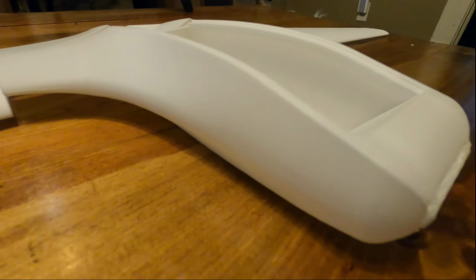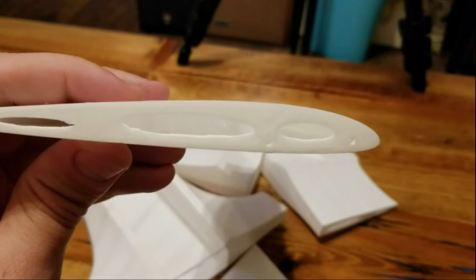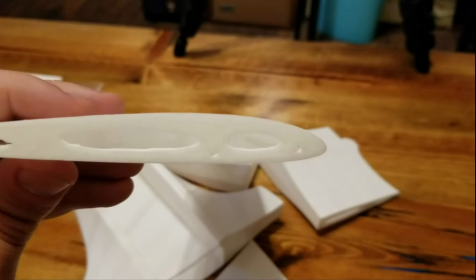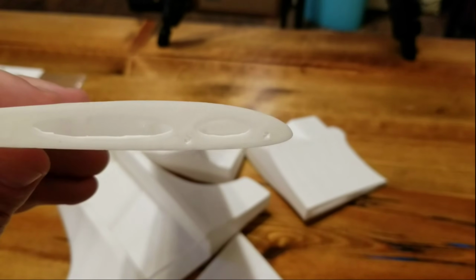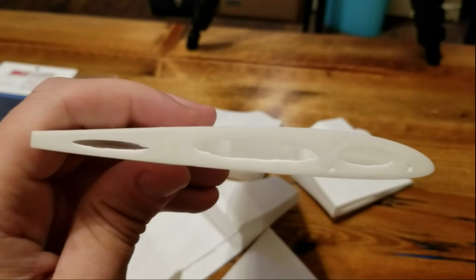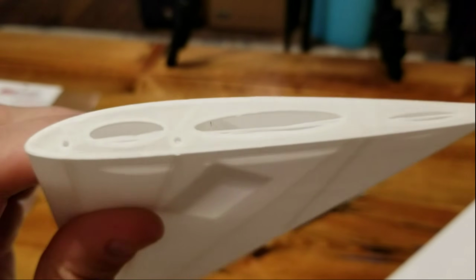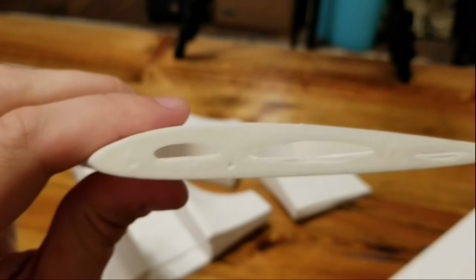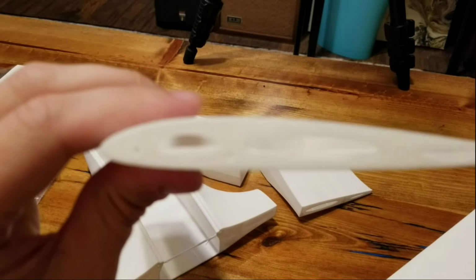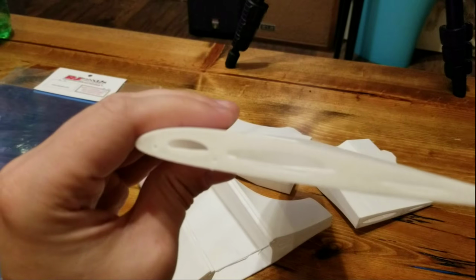I ended up with a full set of parts from Brian, which were printed per the original 2019 design files, but with one modification. The direction parallel to the wingspan was scaled up by 150%. The two other axes were left at the default 100% scaling per the original models. This resulted in a stretched airframe, with a much narrower aspect ratio wing. In the end, I think the additional wing area is good to help get the plane airborne.